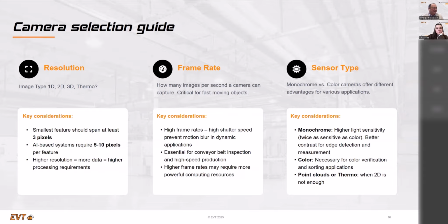So you have to think what is the right resolution pixel-wise. I just mentioned it. If you want to measure, and if you don't trust in the subpixel idea, you need more pixels to define the accurate measurement. So let's say you need 3 pixels to get exactly the resolution you want to have.